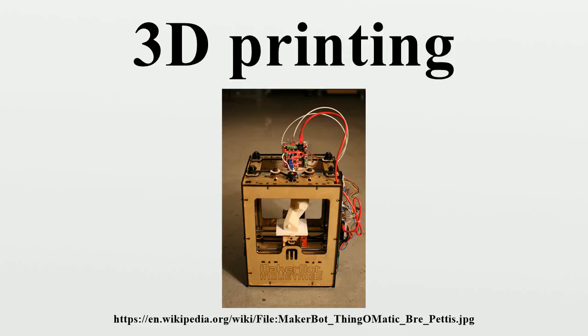Ultra-small features can be made with the 3D micro-fabrication technique used in multiphoton photopolymerization. This approach uses a focused laser to trace the desired 3D object into a block of gel. Due to the non-linear nature of photoexcitation, the gel is cured to a solid only in the places where the laser was focused, while the remaining gel is then washed away. Feature sizes of under 100 nanometers are easily produced, as well as complex structures with moving and interlocked parts.